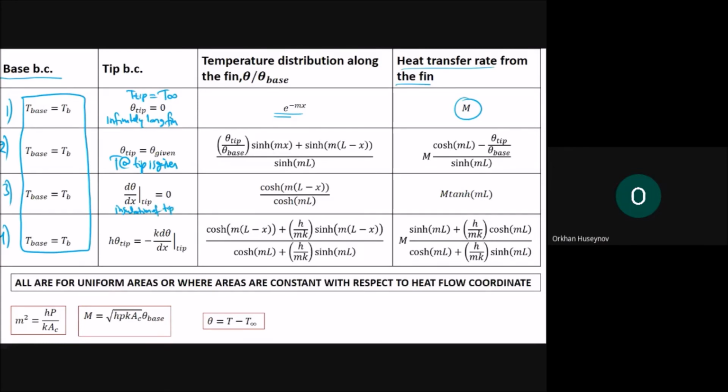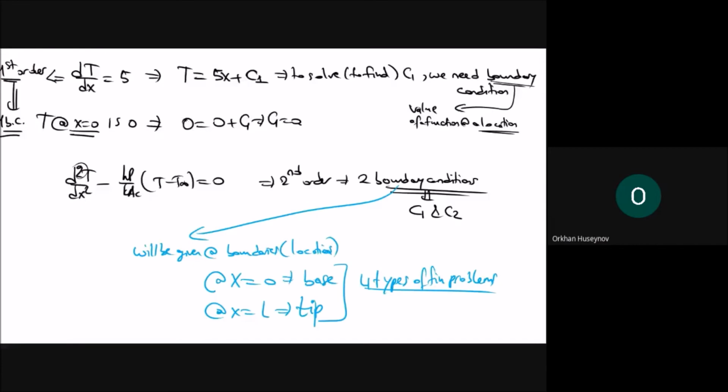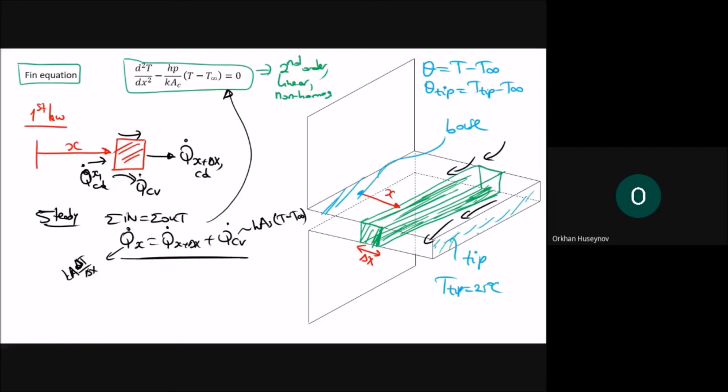of the tip. So if you insulate the tip here, you will not have the heat transfer in that direction. If I just go back to here, if you have the insulation, Q dot by conduction will be 0. What was the equation for Q dot? K A dT by dx is 0. K and A are constants, therefore dT by dx is 0. This one is for insulation.